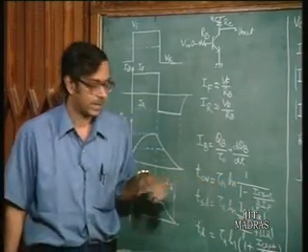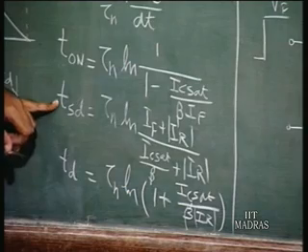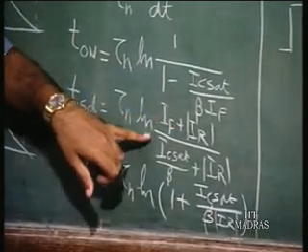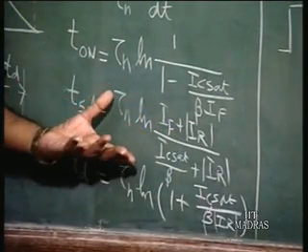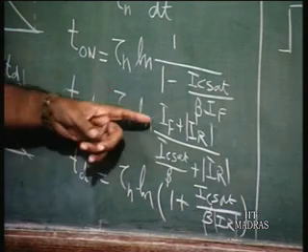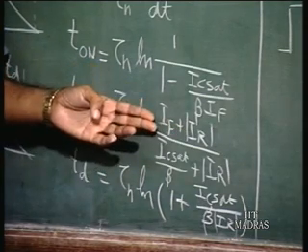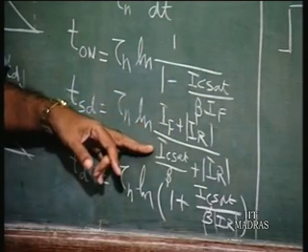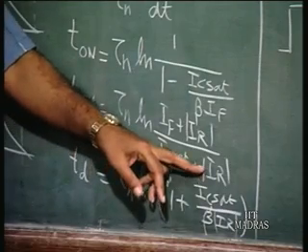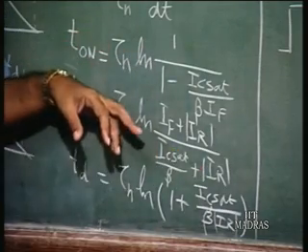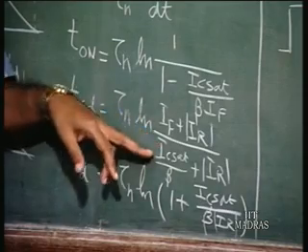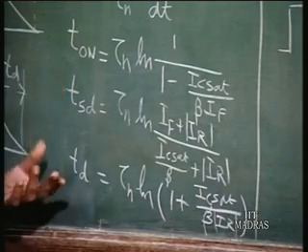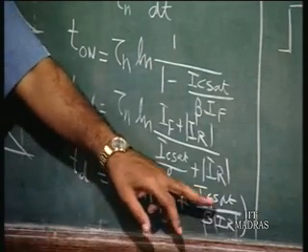It remains the same. What if you take T as D, this relation, the stored charge delay? Again, both the numerator and the denominator would change by the same amount if you change RB and RC by the same factor. If you increase RB, both IF and IR would reduce. IC sat would also reduce if you increase RC, and IR would also reduce. If the change in the resistance values is the same factor, this factor remains constant. No change in TSD, even TD. IC sat by IR remains constant.